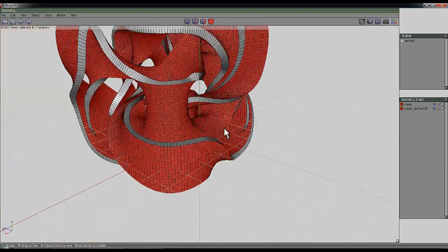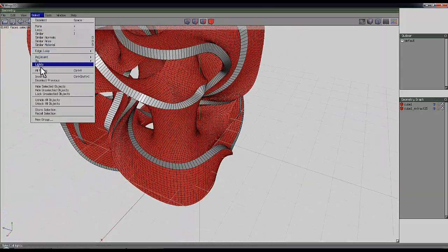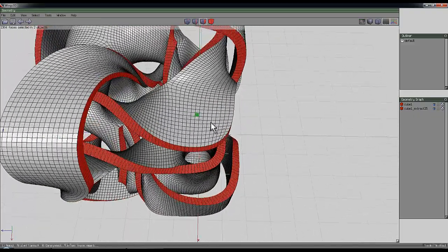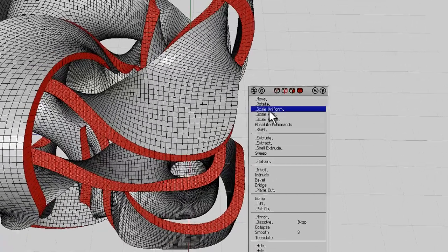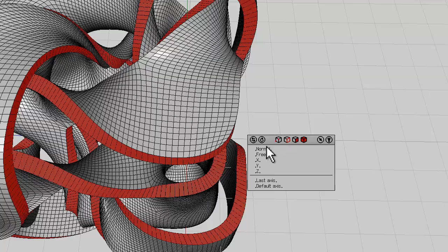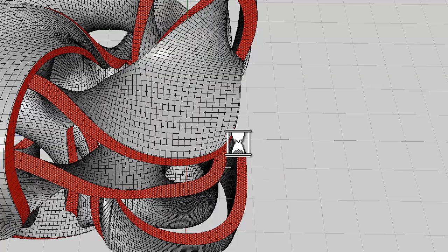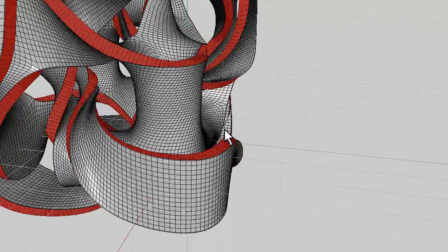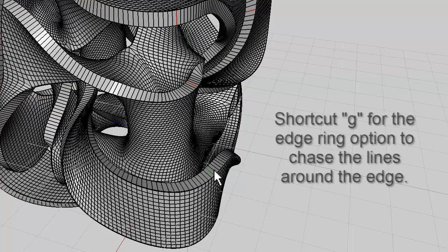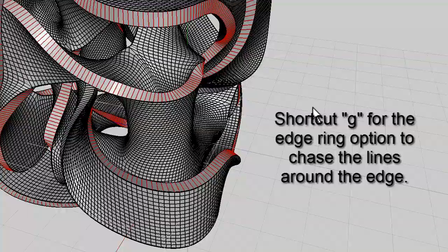Right, when you've done that, you can select and inverse, and then get in a position where you can see this top edge. Right click, and you want to do an extrude, but only a very small one. So extrude it ever so slightly, and then you need to get hold of these lines again. So it's just a matter of selecting a few of these and hoping you've managed to find everything.